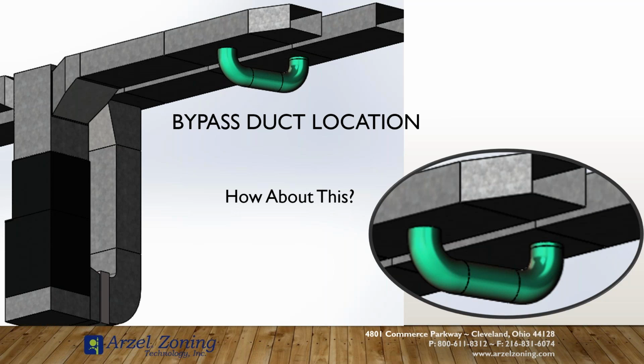Now, I do have one question about that. Is this supposed to happen before zone dampers? No, I'm not so concerned with that. Okay, because that's the only question I have. I'm not so concerned that it happens before your zone dampers. I'm more concerned that it happens before your first reducer. So if you've got 8, 12 feet of let's say 24 by 10 duct, and then you're shrinking it down to an 18 by 10 or something like that, I'd like to see it about 12 inches before that reducer shrinks it down.